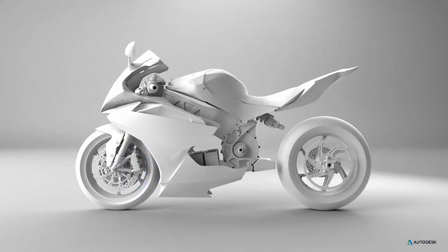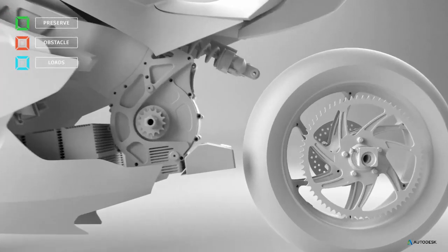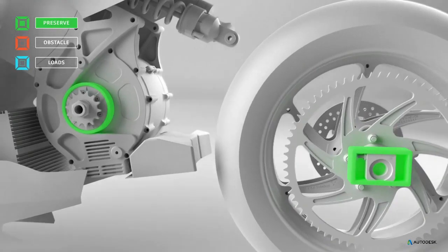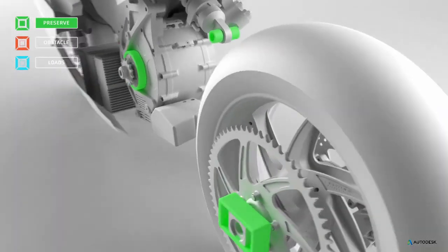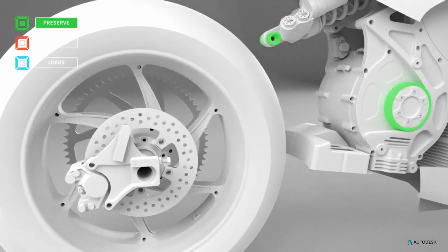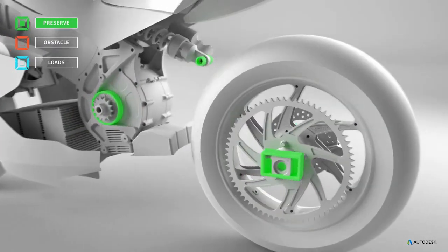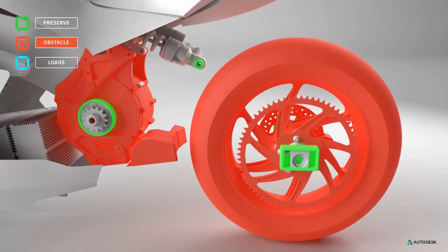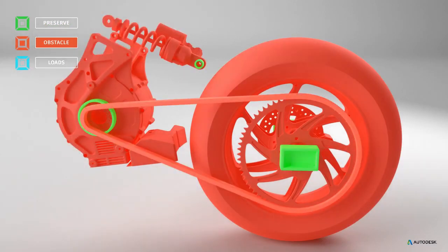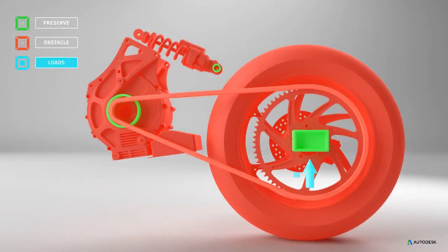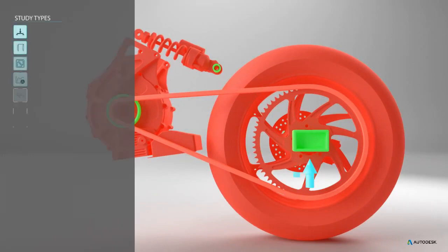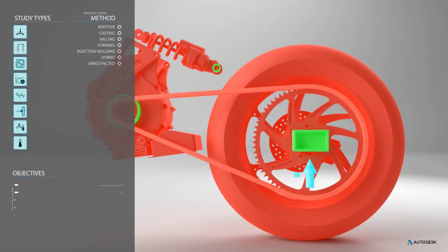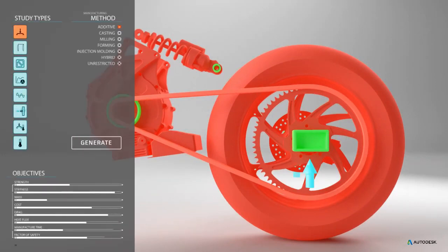Take a look at this illustration. It's a great example of the generative design process. Rather than the typical approach to modeling a form, engineers will enter the problem to solve for first. Where's the model being held down? What areas need to be avoided for collisions? What are the loads that it has to withstand? Are there any alternative materials and manufacturing methods that can be explored?